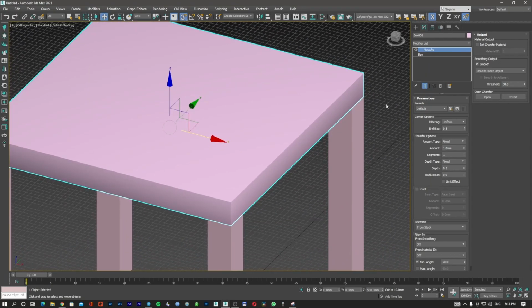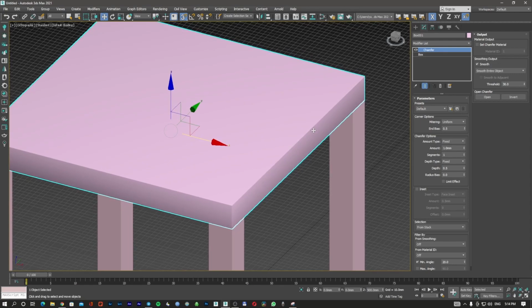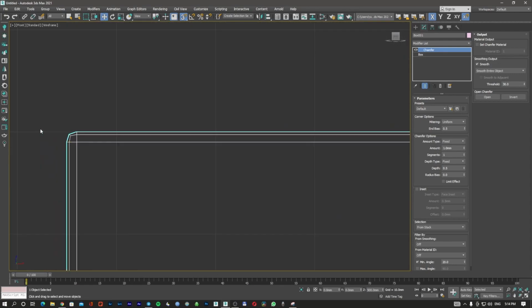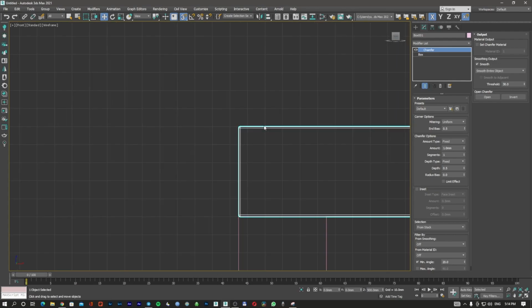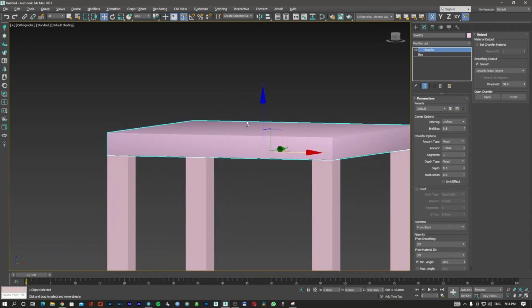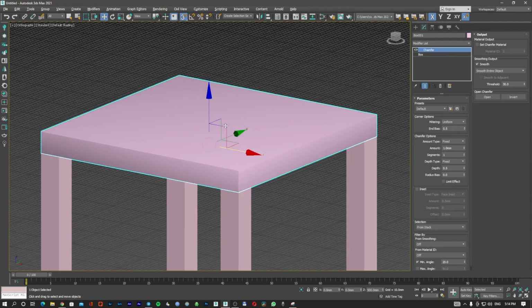The only problem is that, as you can see, if you push this I with the left mouse button, it's just showing you on and off the chamfer. But in the moment that I'm pushing on, this doesn't look straight anymore. It looks kind of a bump, like a curve, because the program is trying to chamfer also. Even though here it doesn't look like it's round, in the 3D it feels like it's kind of round, see? And that it's coming from the chamfer properties, and it's coming from here, the smoothing output. It smooths the entire group, the entire object.